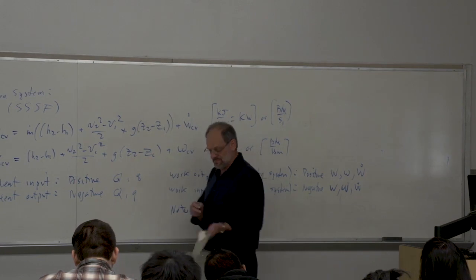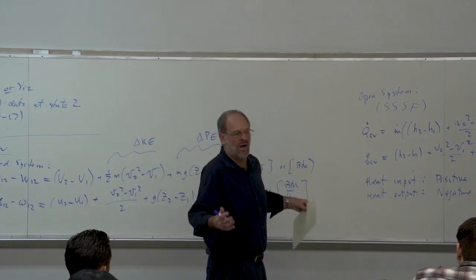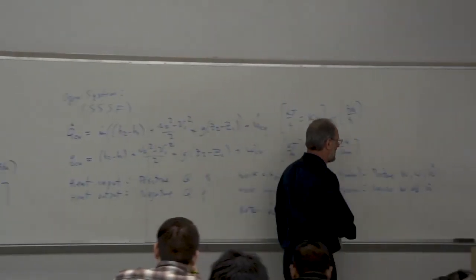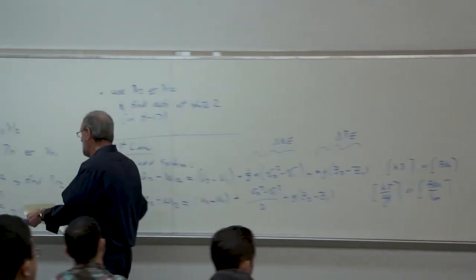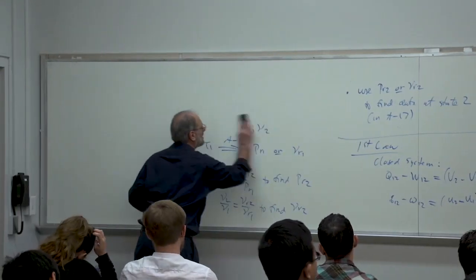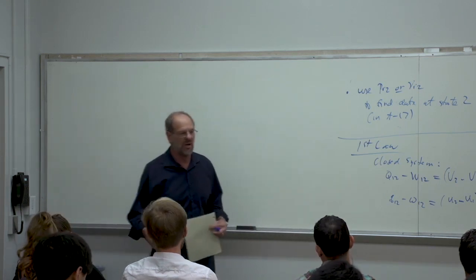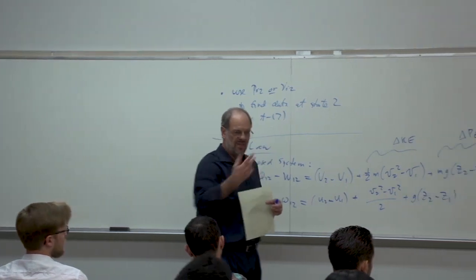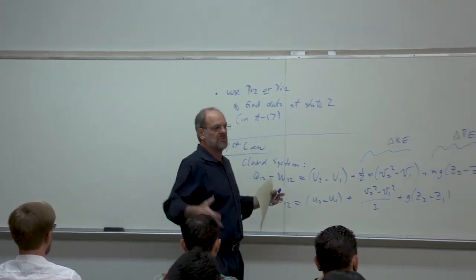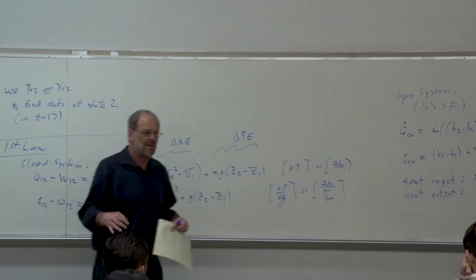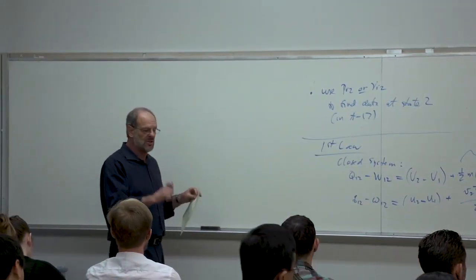Now, where do we use this set of first law equations? Well, really everywhere for all sorts of problems. But what I would like to do is just emphasize those types of processes that we're going to use in this class. And they generally deal with steady flow devices, single stream steady flow devices, the same ones that I keep mentioning: pumps, turbines, and compressors, right? If we're dealing with a cycle, within that cycle, we have pumps, turbines or compressors, right? Pumps provide the work input, compressors provide work input, turbines provide the work output. So these various terms, we're going to have to apply specifically to those devices.